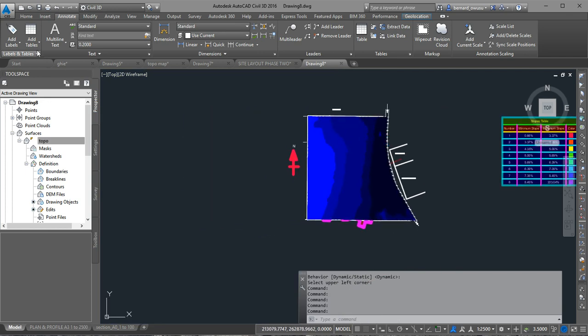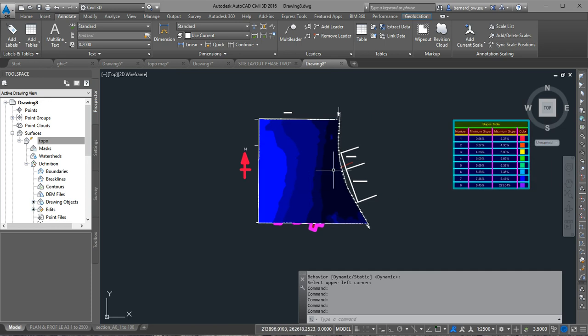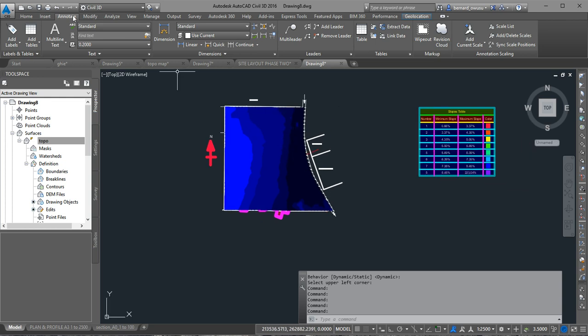So you remember, go to add tables and annotate. Yes, go to display, and elevation should be on, slopes off, so that you see the color scheme for the elevation. Have you seen it? Please, are we all here? Yeah. Good. So go back to annotate, add tables, then you add surface legend table.